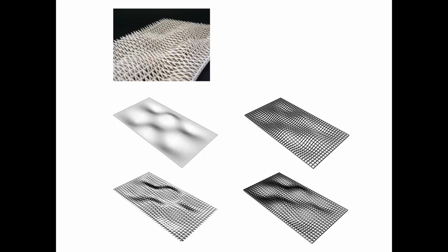A two-way grid, a two-way set of ribs that can then be laser cut and then notched together. The end result will be a set of ribs that you can nest together, take to the laser cutter, cut out, and then start to notch back together for assembly. Later on, we'll take each of those cells and populate each one with a custom shade component that you'll develop.